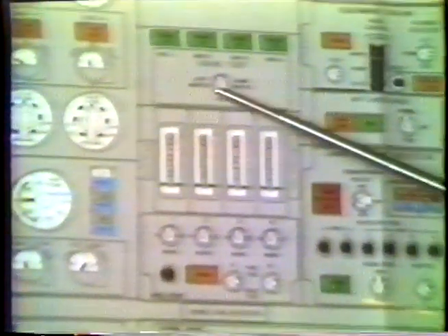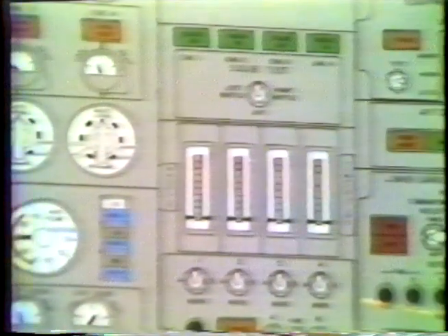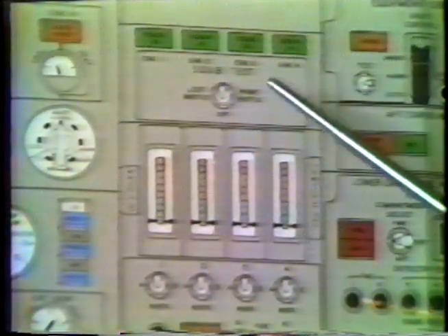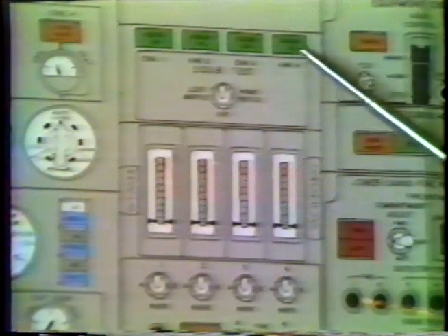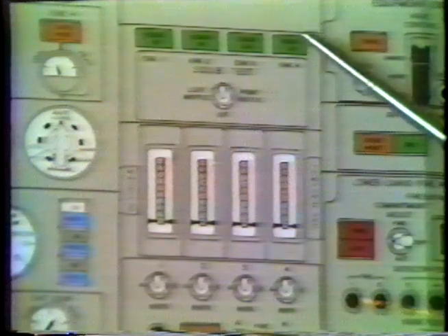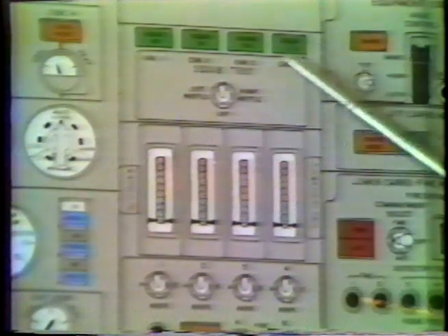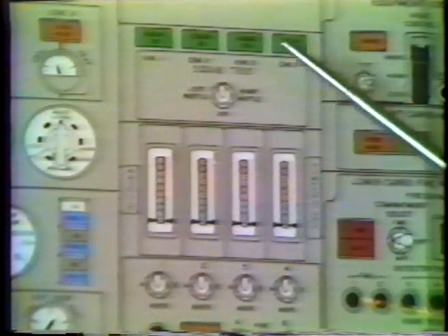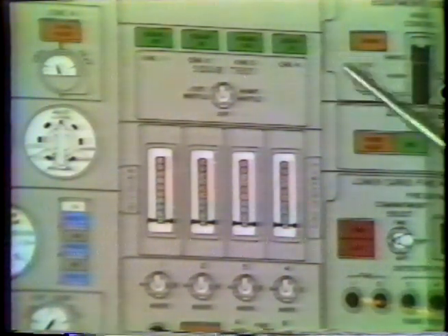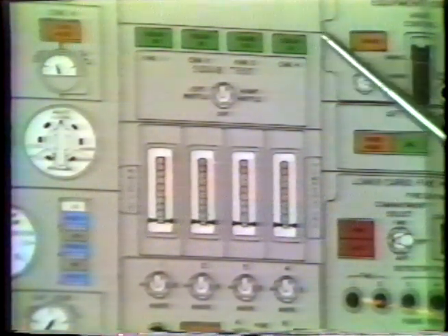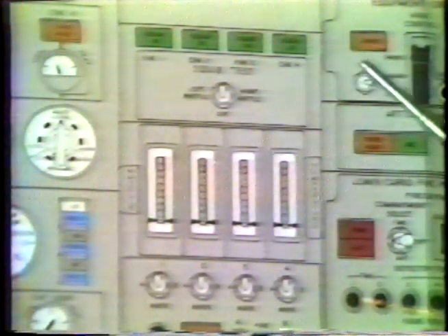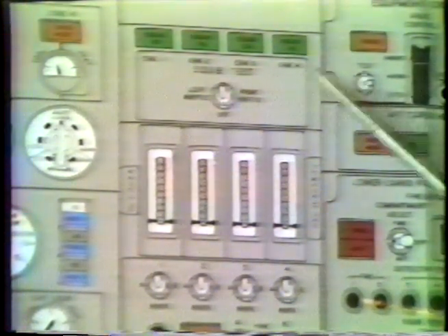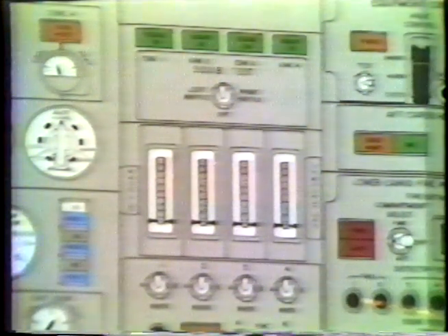First, we talk about the squib test. The squib test simply sends a small current through the discharge unit, which ruptures the Freon bottle to supply Freon to the engines. And when we do a squib test, all we're assuring ourselves is that this unit that fires into the bottle has not been discharged. It does not tell us that the bottle is good.